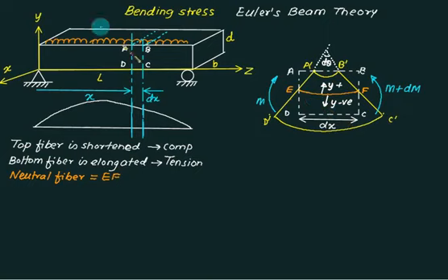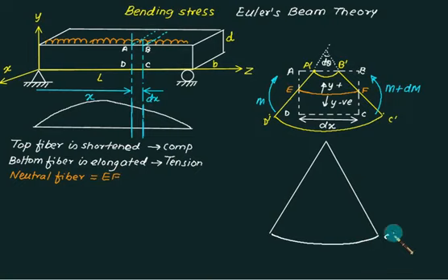Now I suppose the figure has become a little bit complicated, so we'll draw a separate figure. Now this member I will call C'D', and this member we are calling EF. EF is called the neutral plane. With reference to this neutral plane, we'll measure the radius R. This is called the radius of curvature, which is denoted by R or rho. And then we have one top fiber, somewhere here. This top fiber is basically A'B', and this angle equals del theta.